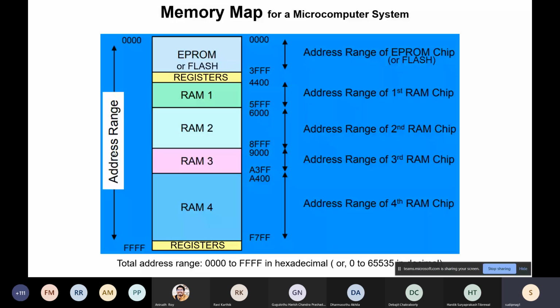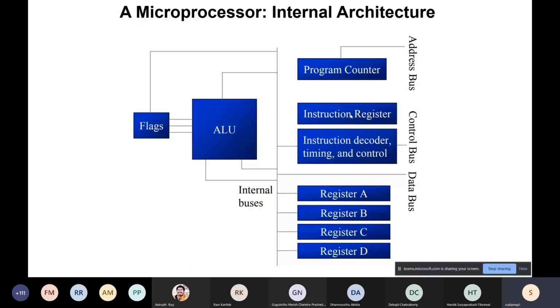So the first instruction is sitting in the instruction register, and then you have to decode. You have fetched the instruction. Fetch, decode, execute are the three steps we wanted to do. We have just fetched the instruction in the instruction register. After this fetching, I have to decode. You can understand possibly by now that an instruction decoder is there.